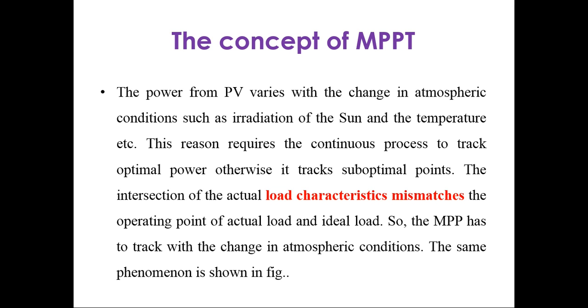Before proceeding further, let's begin: what is the concept of MPPT? If you have gone through the lecture where we incorporated the DC load, the operating point on the IV curve was the concept. So let's revise this concept. The operating point of the load is the point at which the IV curve of the load and the IV curve of the PV intersect.